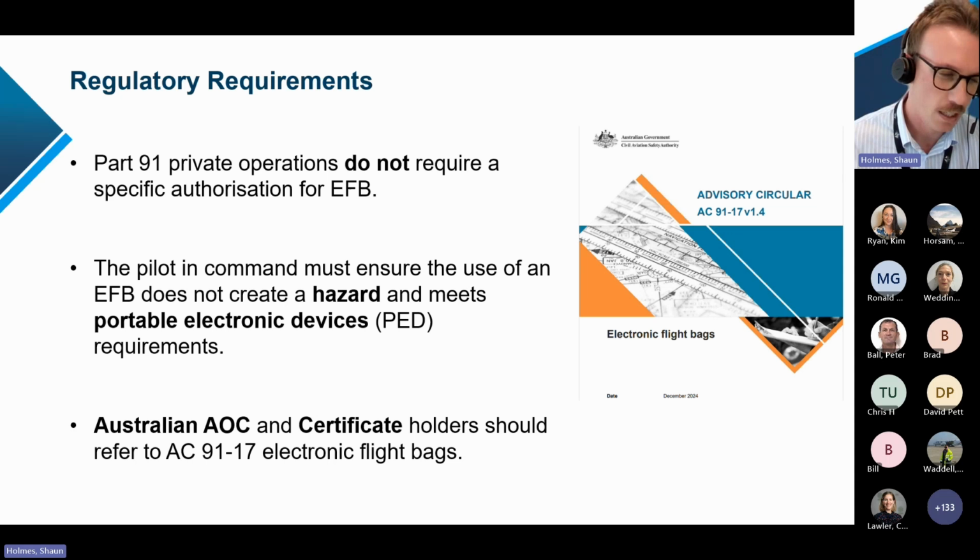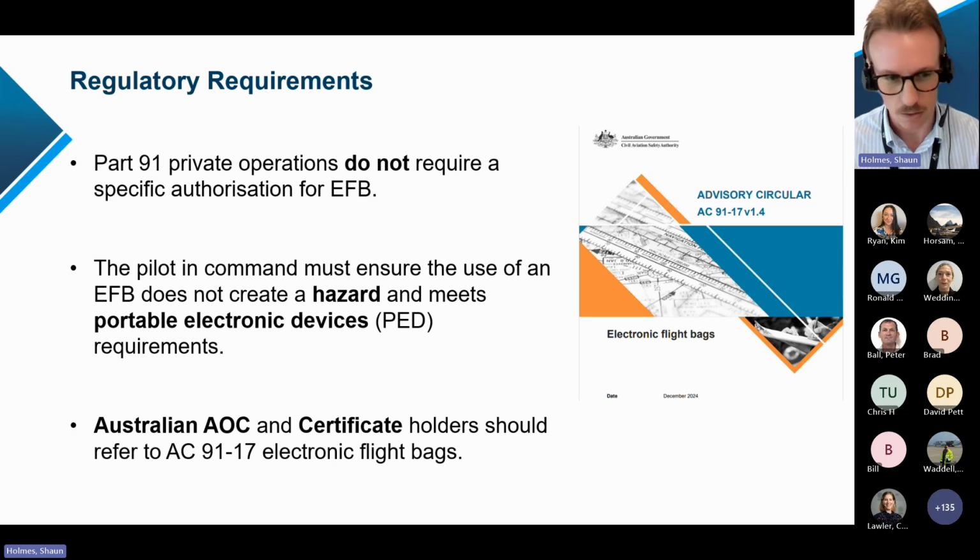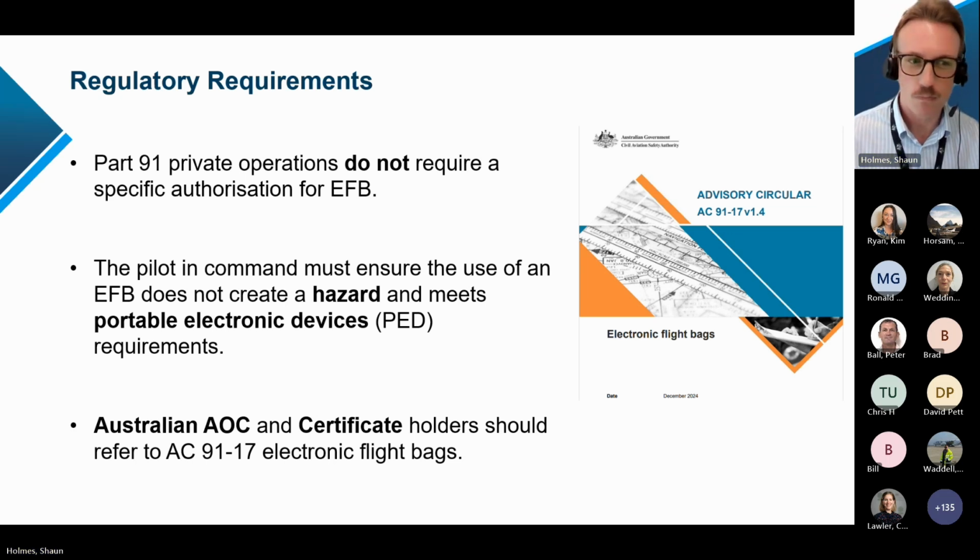Not specifically relevant to you using an EFB, but the other part of portable electronic devices is that as the pilot of the aircraft, you need to ensure that if you are using a portable electronic device, that it does not distract you from performing your duties for the flight. So reasonably straightforward in that respect, and not requiring a specific authorization from CASA to do so to start using that EFB.